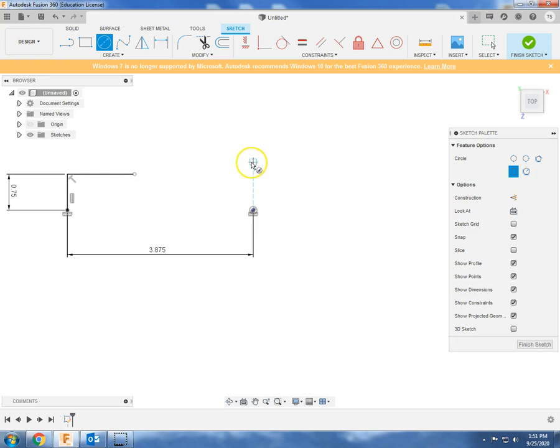What that does, that's going to put that circle in the same vertical line as my origin. It works the same over here. You see I'm switching back and forth. So I'm not really worried about it capturing on that line. I do want to capture it on this. So I'm going to do my circle.